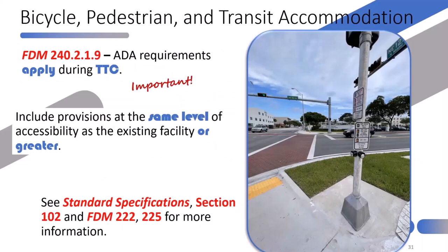ADA requirements are in full force and effect during temporary traffic control. And we are required by this language in the FDM to provide provisions for pedestrians at the same level of accessibility as the existing facility. Now, a distinction to that is if we're building a brand new sidewalk in a place where sidewalks did not otherwise already exist, then pedestrian accommodations are not necessarily required.